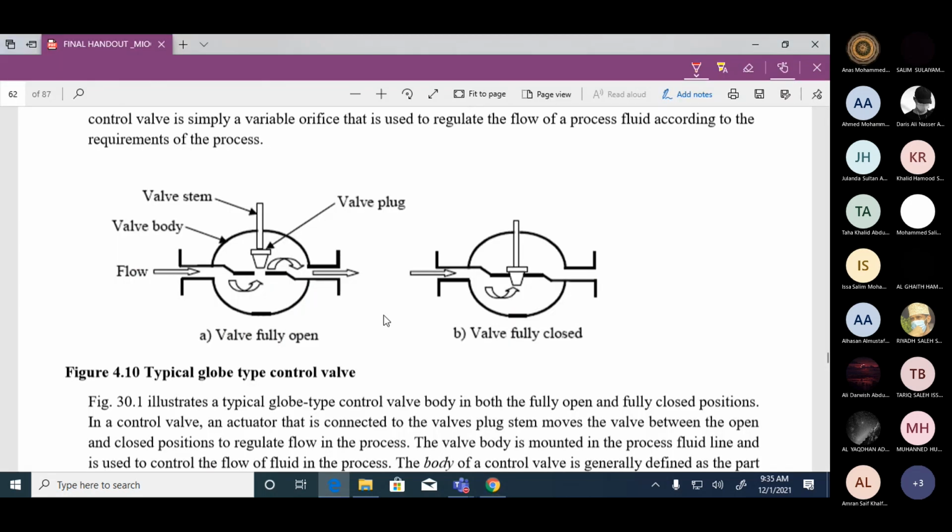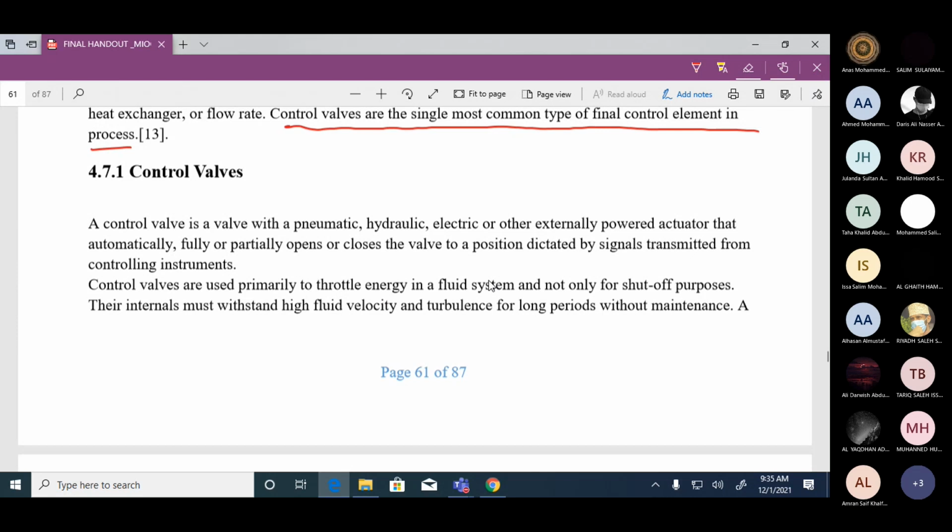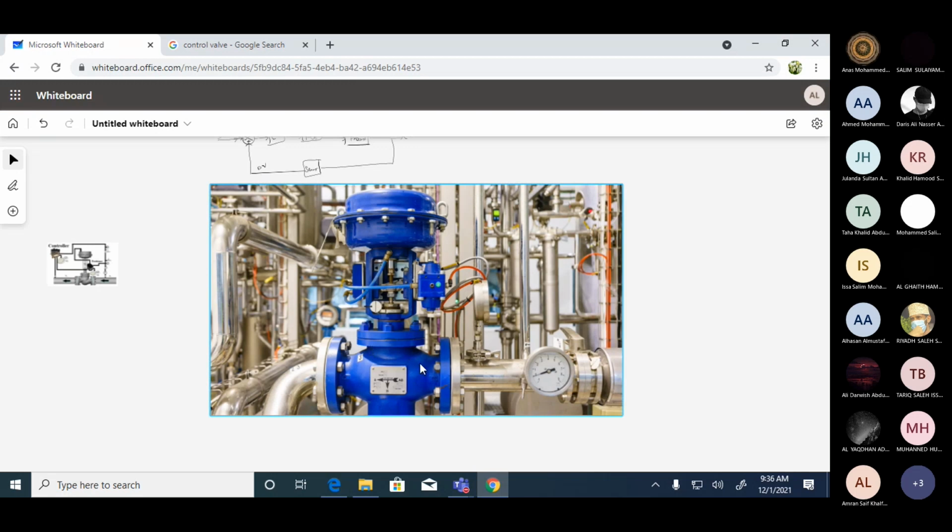Okay, so the control valve that we are going to be looking at in detail depends upon how the valve can be opened and closed. We have to see that. Basically, a control valve is operated hydraulically, pneumatically or electrically. If you look at this picture, if you want to open the valve, that means push it open, this actuator has to move up. The actuator has to move the valve stem inside up. Then only it will allow the flow to go.